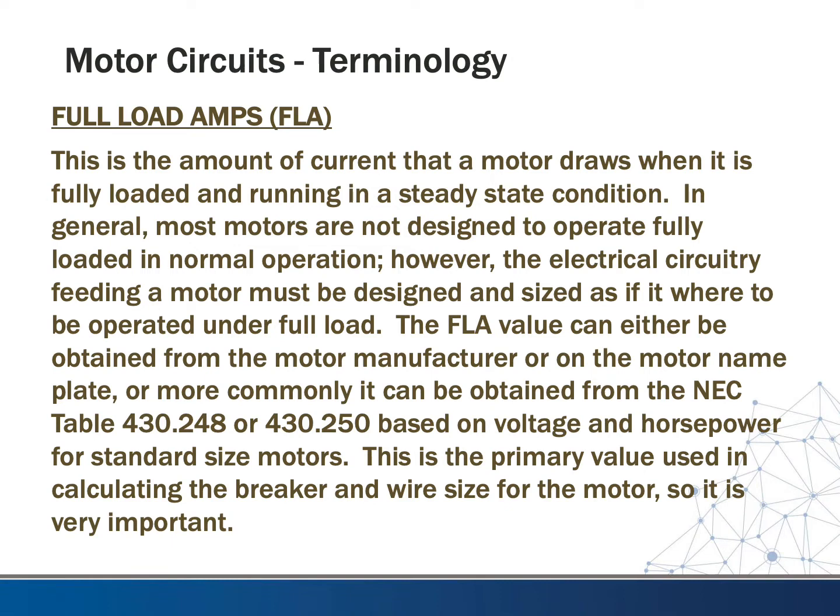This is the amount of current that a motor draws when it is fully loaded and running in a steady state condition. In general, most motors are not designed to operate fully loaded in normal operation, at least not all the time. However, the electrical circuitry feeding a motor must be designed and sized as if it were to be operated under full load.